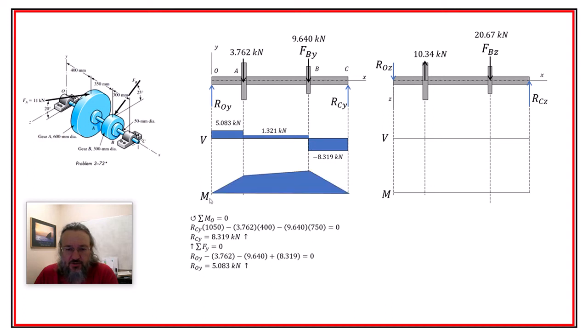So when we go to do the moment diagram of this, we have a sloping upwards, so that we get this value, and then it continues to slope upwards. And then when it gets down to B, it starts to slope downwards and goes to 0, of course, because there can't be any moments at the ends of these kinds of bearings. We're treating it as simply supported. And so we get the moment right here.